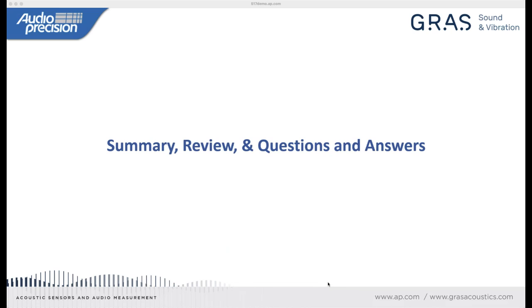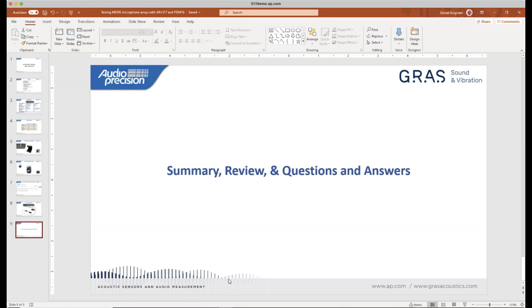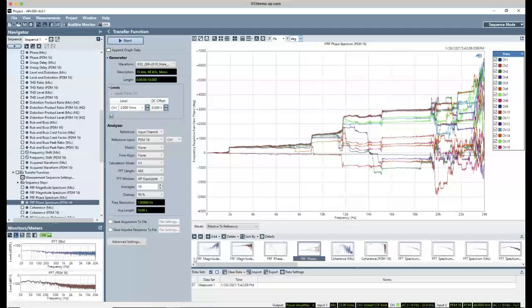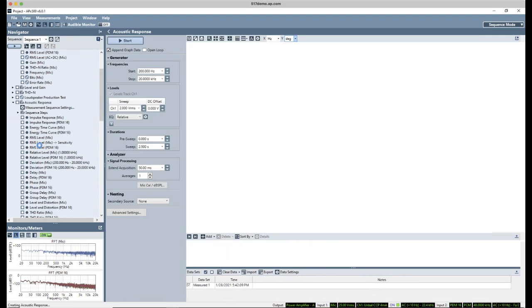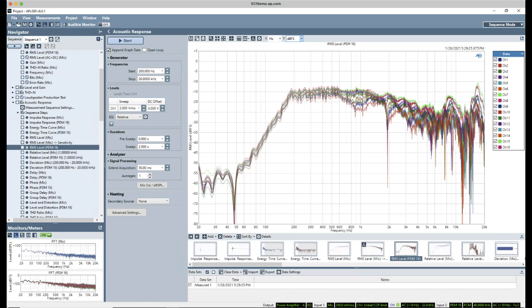Yeah, that's actually a test I've had to do on a production line many times. We call it a mic seal test. You might call it the same thing. So let's go back and look at frequency response. And actually in this context, it doesn't matter too much if you're looking at the absolute or the relative frequency response.